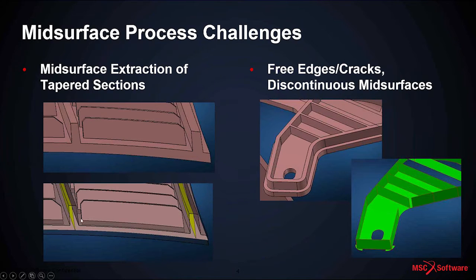And the challenge for us is to really create a mid-surface piece that is aligned to the midline of the section. And as you saw earlier in the presentation, I had an example where there must have been dozens of these ribs, all of which are using draft, all of which you have to be very careful when adjusting the mid-surface at the midplane. Here on the right, more examples of these ribs.